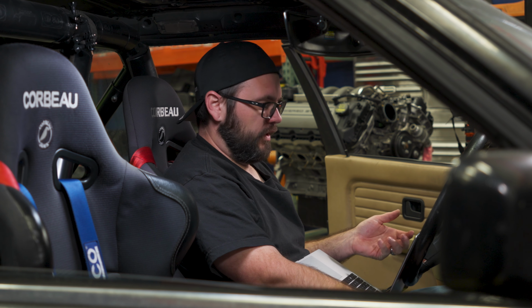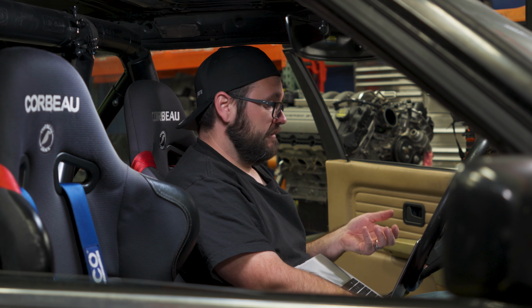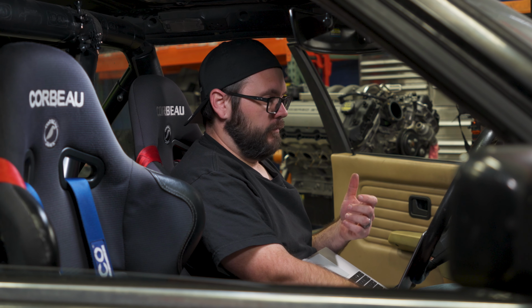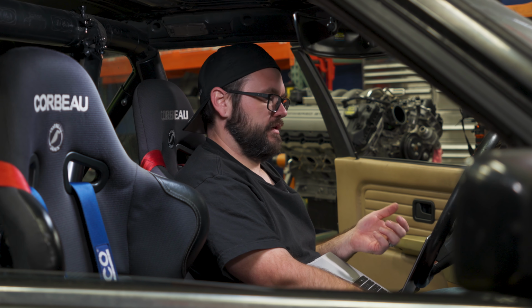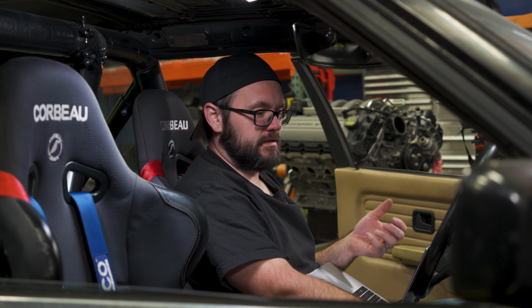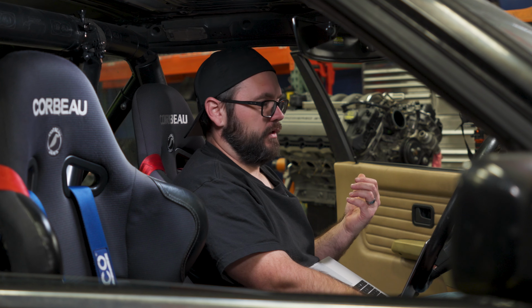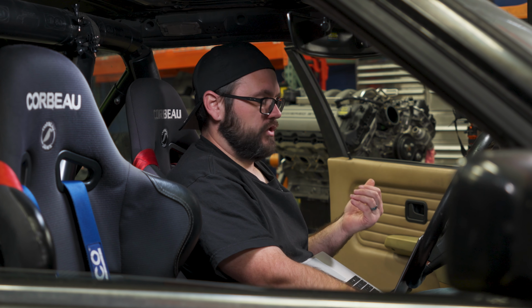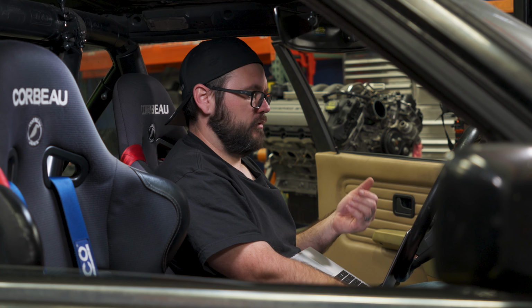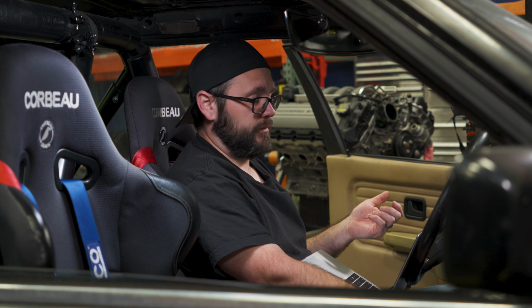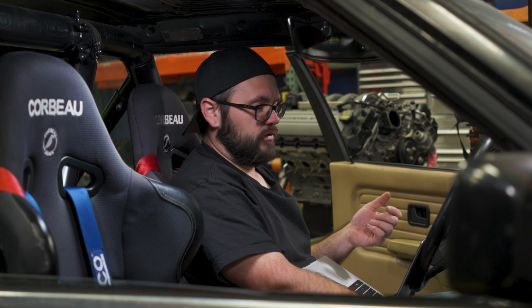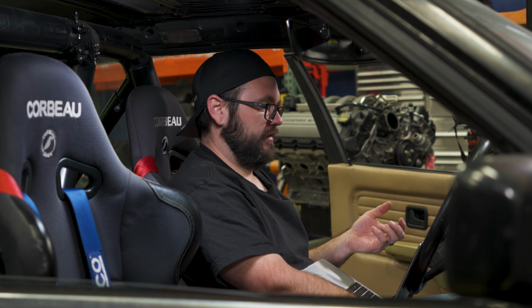Okay, now that we have the firmware updated in the ECU, what we need to do is modify the tune for the modifications done to the vehicle. Now, a single set of long tube headers is a modification that does change airflow requirements, but it's not a major mod. It's going to affect air fuel ratio in a few key places. We're probably going to make more torque across the board. However, that's a minor tuning thing.